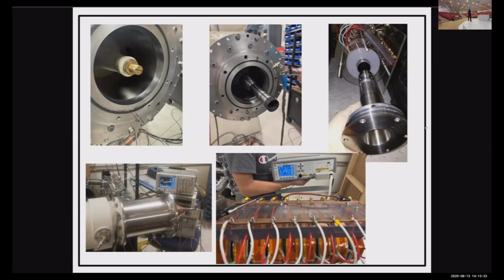Why are we using tubular and annular types of cathode? Because we want to generate higher current. They found that if you have a solid cathode, your current can reach kiloamps, but it's not that high. If you have a knife edge cathode, you will emit a very thin electron beam, and the current is high. So we put everything under solenoid coils, as you see here, and then we insert the slow wave structure, and now you have the system.